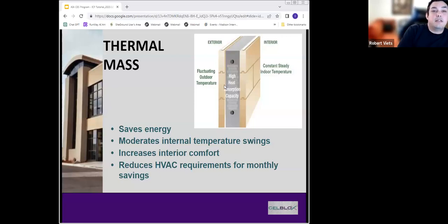The EPS foam on the ICF wall, when the block is just empty, is technically an R24. But once the thermal mass of the concrete is added and is interacting with the earth, the ICF structure will consistently outperform even an R60 building for those reasons.